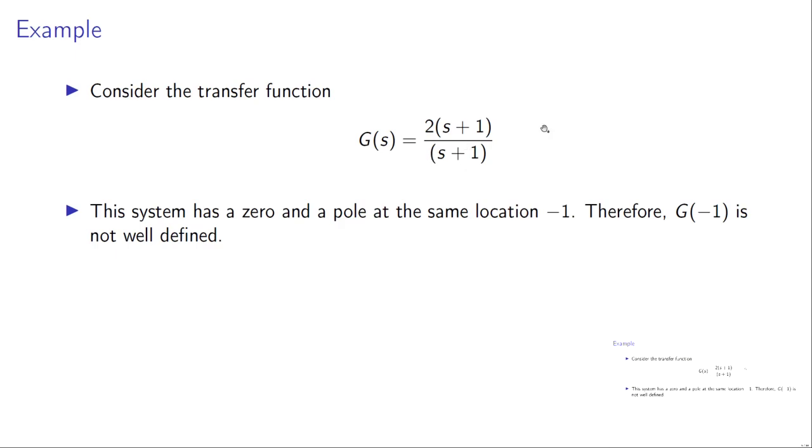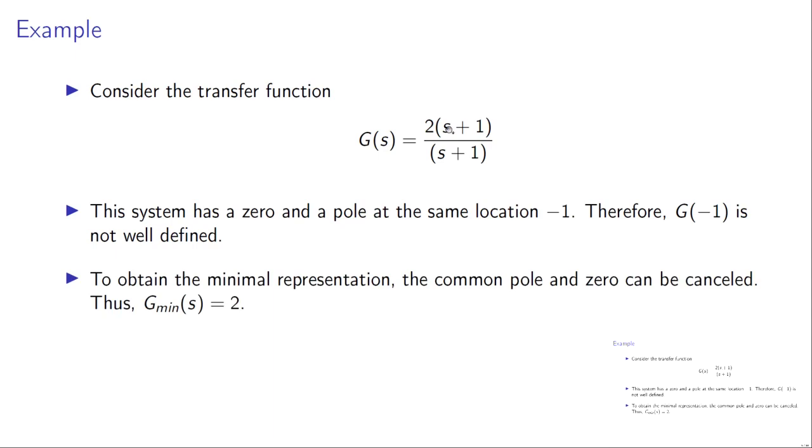You could design a controller that would cancel the unstable pole, but in real life the cancellation cannot be perfect, and then you still have something that will give you undesired dynamics in the closed loop system. So we need to be careful every time we have cancellation of poles and zeros.